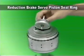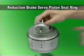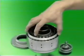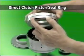As for the 5-speed automatic transaxle, the existence of any possible damage of the seal ring installed at the servo piston of the reduction brake should be checked. Also, check for any damage of the seal ring installed at the direct clutch piston.